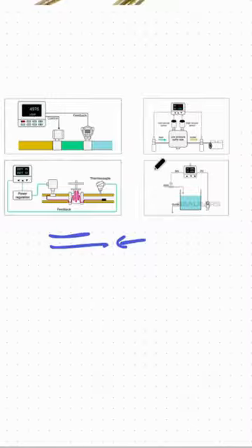After seeing all these advantages, there are also a few disadvantages of a PID controller, such as it is not an optimal controller. We have to define the values of three variables, and there is no particular solution. So in large industrial applications, PID controllers are not used. For example, other better options are there, so PID controllers may not be used. Also, PID controllers are not well suited for non-linear systems, as they work best for linear. In complex systems, their performance may degrade.